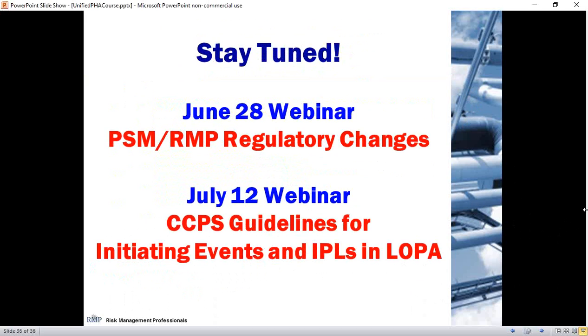To the extent practical, if it's a typical control valve station where the block valves are readily identifiable, perhaps the probability of leaving those valves closed is overreached by the failure probability of the control valve to close or a transmitter to fail to cause the control valve to close. In a case like that, perhaps you can lump them together, but that has to be done with an understanding of how it relates for potential common mode failures to your safeguards.